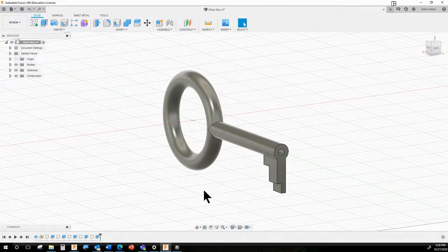Okay, so now what I want to do is show you chamfer and fillet. A lot of times when you have sharp corners like this on things, when people manufacture them, they just give them a little bit of a chamfer. So they just knock off the corner. And if you look at any table you're sitting at, I think we talked about this when we were doing Tinkercad, when we talked a little bit about their little chamfer tool. But generally, things don't have sharp corners on them, so often we will chamfer them.